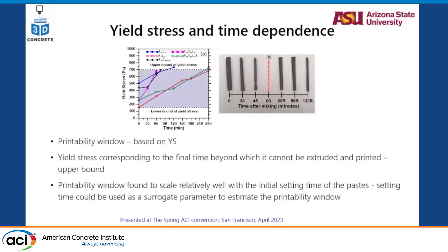Right, so extrusional rheology, we'll talk about that in a minute. But if you look at time dependence of yield stress, you can measure yield stress as a function of time from the mix reacting with water or whatever solution it is. And we said, okay, here is a range that we can simply say, again, very arbitrarily, based on the extrusion setup that we had, based on the rheology measurement that we have, that this is a nice range in which we can say we have a mix as a printable mix.